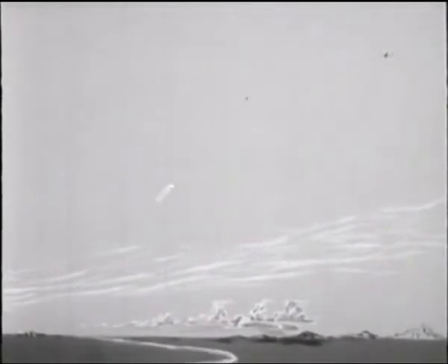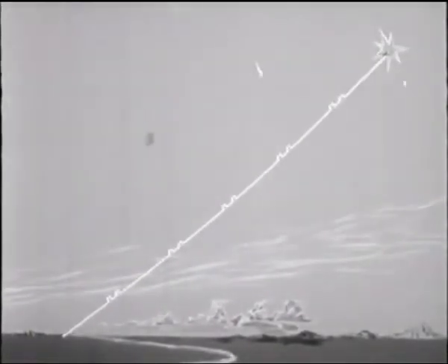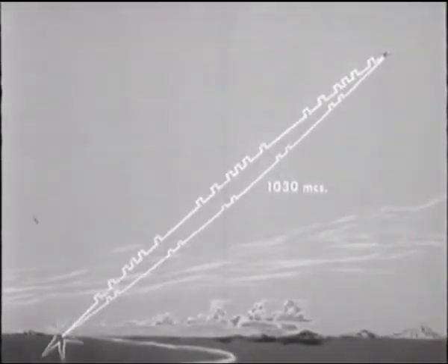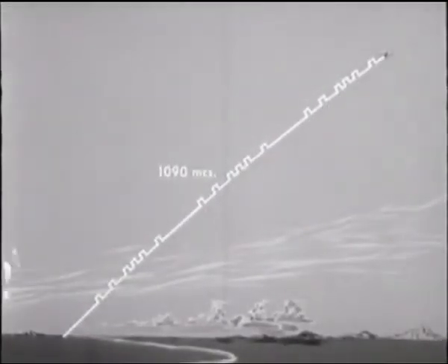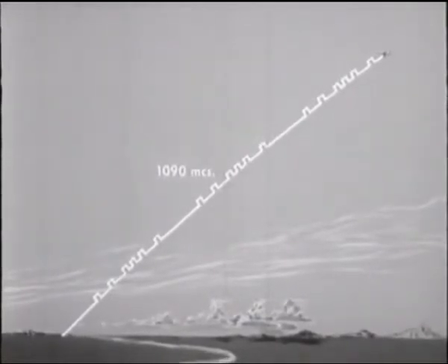Briefly put, secondary radar interrogates, that is, it questions the radar transponder in an aircraft on the radio frequency of 1,030 megacycles. This interrogatory signal triggers a reply from the transponder in the form of a new and greatly strengthened signal on the radio frequency of 1,090 megacycles to the ground equipment, where it appears on the radar display in a distinct form.